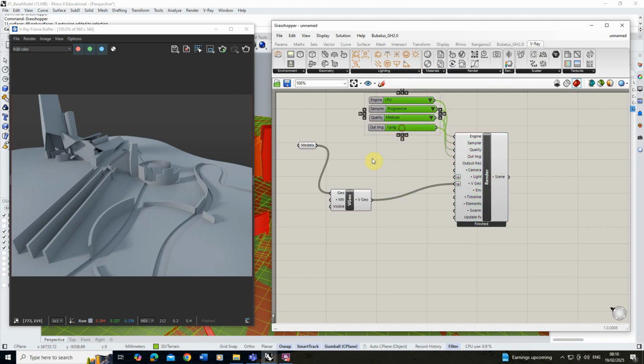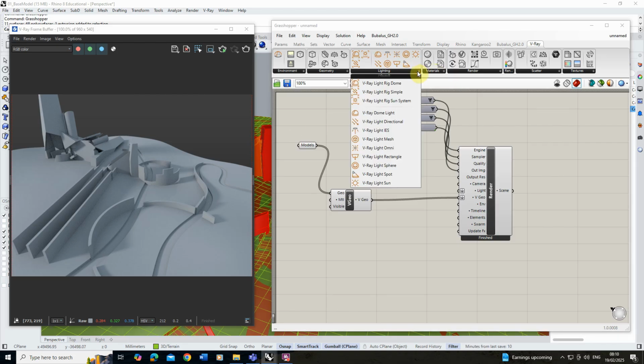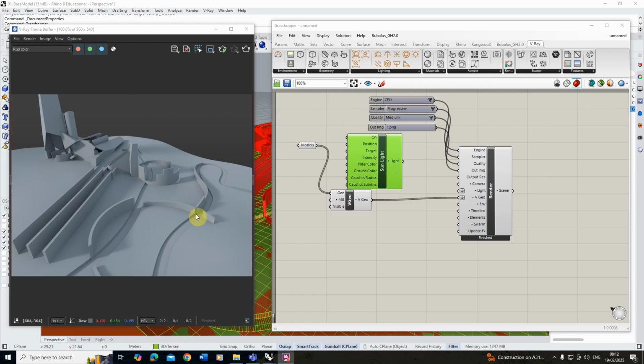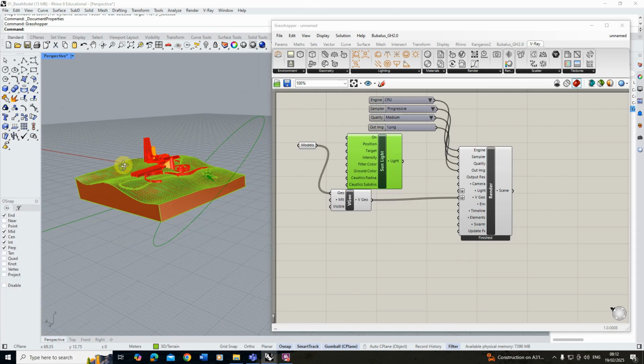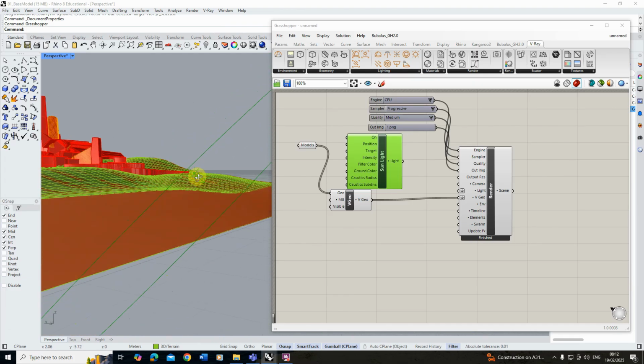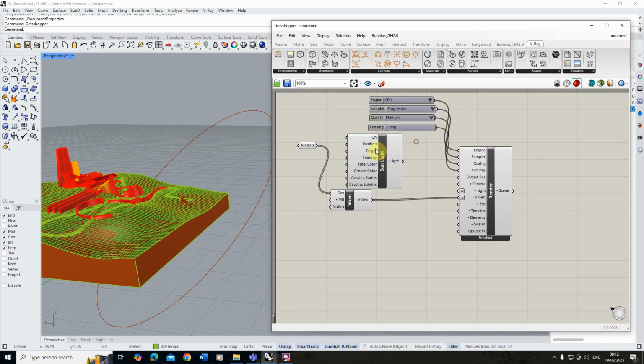Now we're just going to move these out the way. We'll move this down slightly. I'm going to open up this lighting tab, and we're going to start by making a VRay sun here, and this is going to light up the scene a little bit more brightly in my file. Now we've set up this sun, if I minimize my render frame here and zoom out slightly, you can see it's actually in our scene as this green object here, and it's got a direction, it's also got a rough size and scale there. And those are all set by these options here, this position, target, intensity, etc.